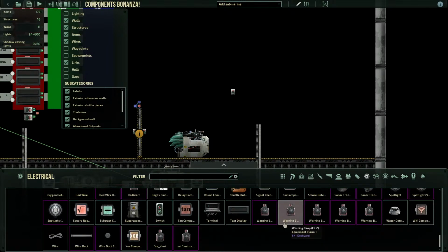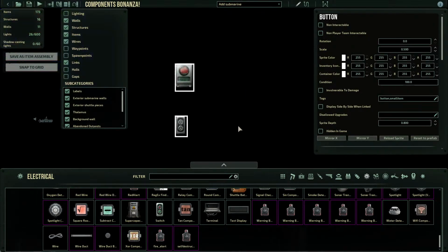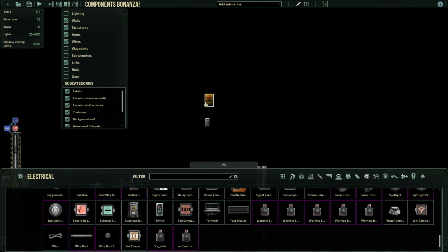So if you look at the outputs of these, if you were to click them each 3 times, whenever you click the button, you get, for 1/60th of a second, because that's the update speed of the data network, a 1 for exactly 1 frame. And then after everything that is connected to it has processed its signal, and the 1 has carried out its effect, then it's turned off, for the next iteration through the cycle.